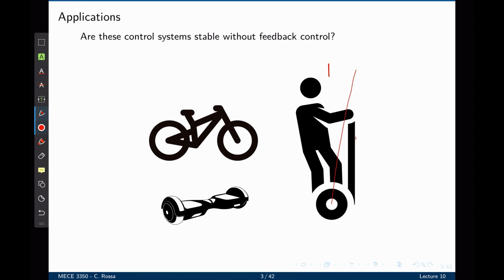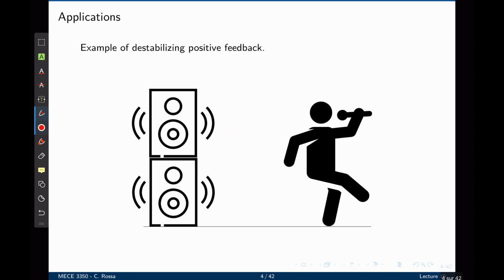The orientation of the Segway with respect to the desired line can be measured and now sent to a feedback control, where the desired position in this case is 0 degrees. Any deviation from 0 degree will create an error, and the feedback control will make adjustments to eliminate that error. These are good examples of naturally unstable systems that can be stabilized using feedback control. In the same way, we can stabilize unstable systems. We can make stable systems unstable if you don't design the controller properly.